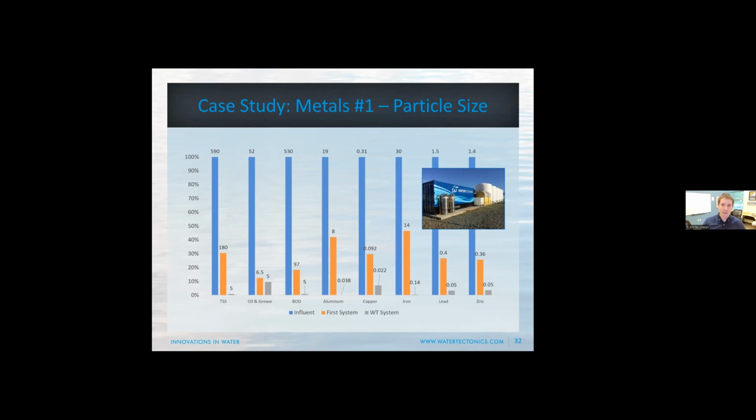And so the larger stuff was getting filtered out by that 20 micron, but the smaller stuff was just going straight through it. So when we retrofitted this system with some coagulation to basically get all those small things to come together and get bigger before we got to the filtration stage, then you can see that's where we go down to the gray line here. We're able to knock those down, use the same filter and have it be efficient, but just get those things larger so that that filter could work and they weren't just slipping right through it.